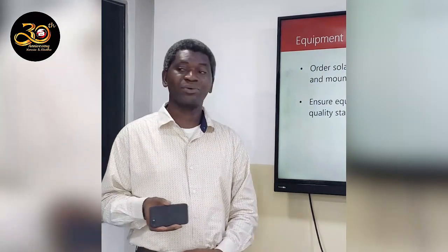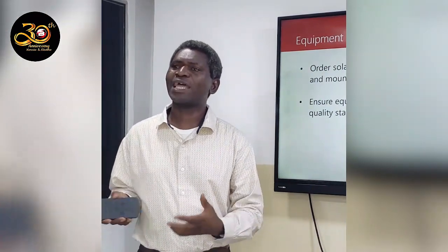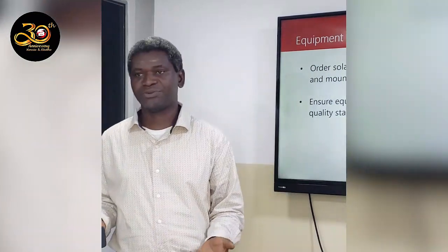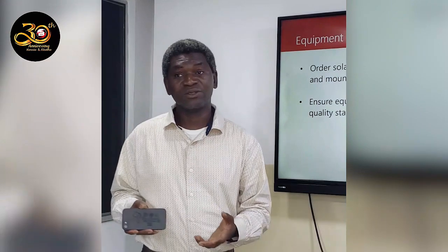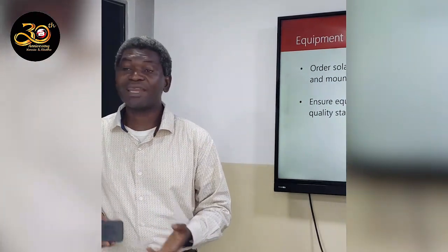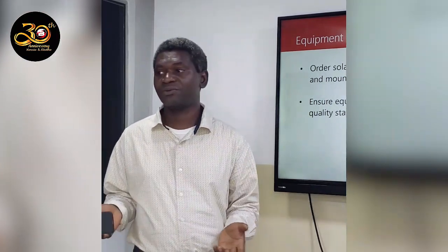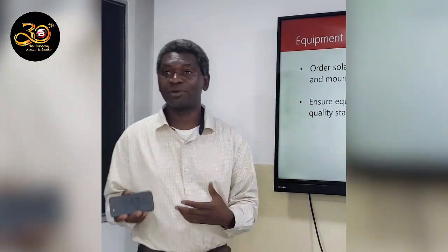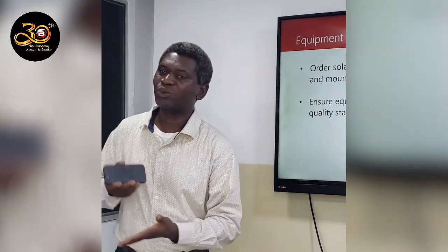I will share an example that happened here also. Sometimes procurement will say, okay, we want to help you save money, instead of you to use a 450 watt panel, we got 500 watts for you. But if you didn't have that engagement with them, to say, look, it's 450 watts I have here, make sure you get 450 watts, by the time they bring 500 watts, you might discover that 500 watts might not be able to work for you at the end of the day. So that is where this comes in. Equipment procurement is very important. So you have to work hand in hand with procurement.